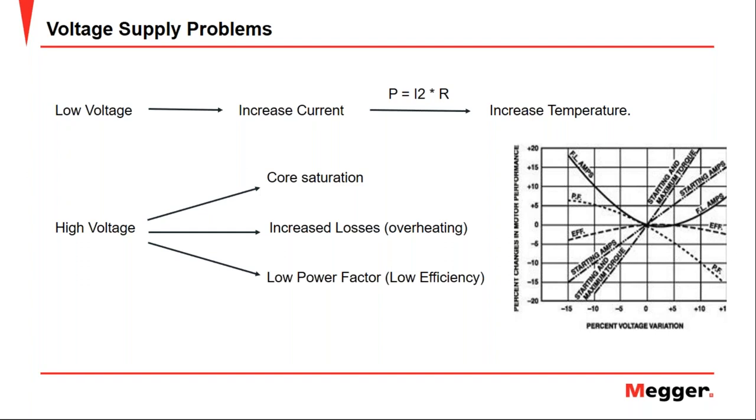Very important to have in mind: pretty much all voltage issues come from upstream. Whatever problem you have with the voltage bus, it will affect the whole voltage bus. It is not only the one motor that you are testing that is in trouble, it is all the motors connected to that bus, thinking about all the row of the MCC at which you are standing, at minimum. Walk upstream, find what causes the problem and fix it. If you can't, make sure that all of your critical motors are derated properly so they are not running too hot.